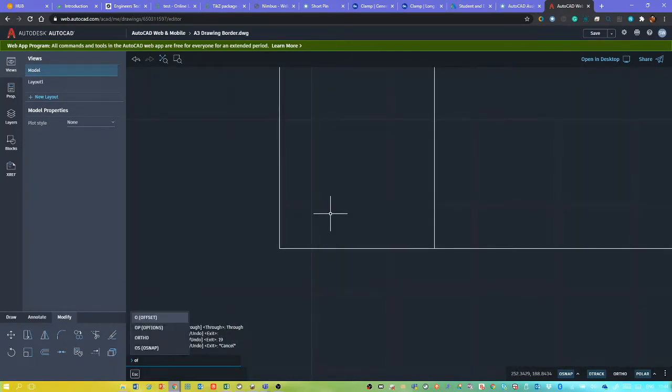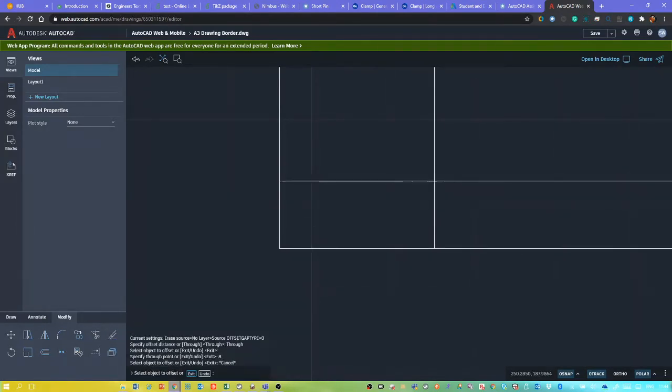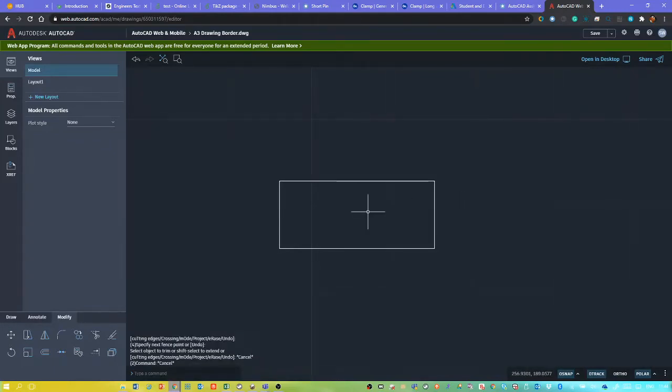We're going to use the offset command again, and this time I'm going to select this line and offset it by 8mm, because if we remember from the drawing, it was 8mm diameter. Okay. I'm now going to use the trim command, so you can see down here I've just typed in trim. The web version is slightly more advanced in that it guesses the lines you want to get rid of. You might find that's the case using AutoCAD 2021. I don't know, I've not had a go with that yet.